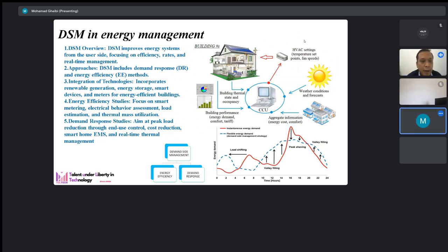You have it. Next. Okay, for DSM, demand side management, this is about energy management and involves several key aspects. For example, DSM aims to enhance energy systems from the user perspective, enabling effective pricing structures and real-time management to optimize consumption. DSM encompasses two main strategies: demand response, which involves adjusting energy usage in response to grid conditions or pricing signals, and energy efficiency, which focuses on reducing overall energy consumption through various means.